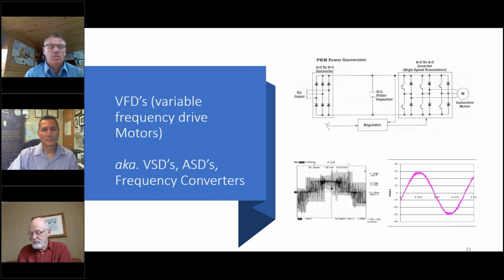There are some mitigations, and a lot of it can be related to lead length. The problem can be exacerbated the longer the cable goes from the VFD to the motor. So it's a complex topic, and one worthy of a future presentation probably. Yeah, I've heard there are rules of thumb as far as cable lengths and wanting to put in a filter.